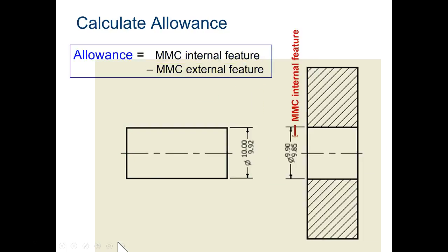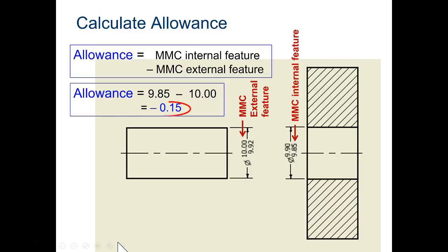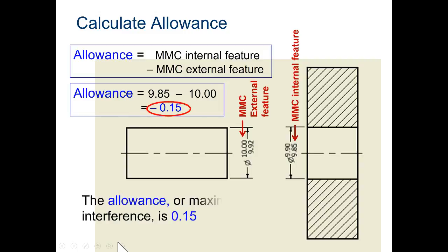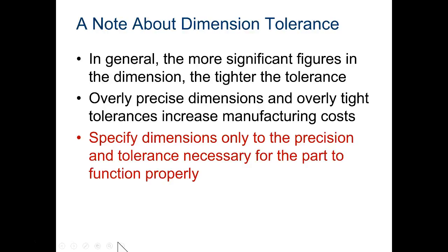I'm not going to discuss that here. I did it in class. This will just be something you need to know for a vocabulary quiz that we'll do on Canvas. Bottom line for dimensions and tolerances: don't require tolerances that are tighter than necessary. It makes it more expensive to produce without adding value. And that's the end.